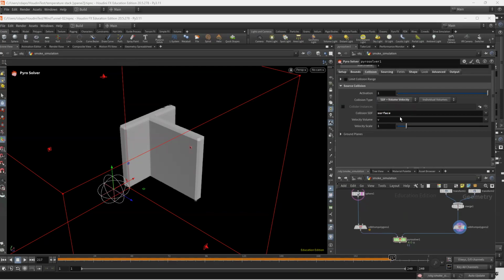What's the purpose of doing that? What is the difference? It works a little better, honestly. But the other reason is if you had a moving piece of geometry, this is the only one that works. Because the way, actually, it's very interesting. The way you simulate moving collisions with fluid dynamics is you give every piece of the surface on its inside a velocity, and then the velocity gets picked up by the simulation.